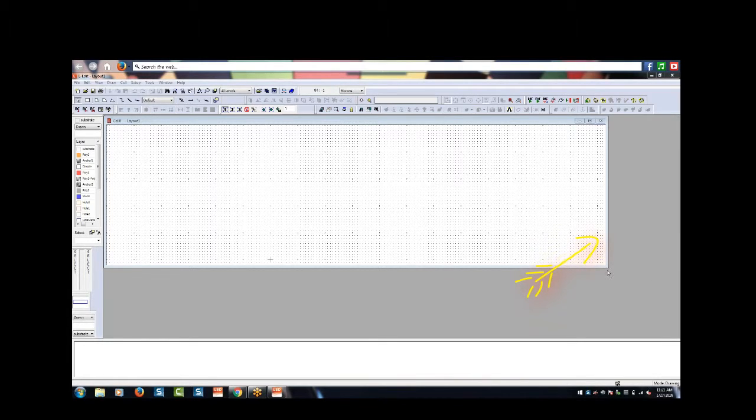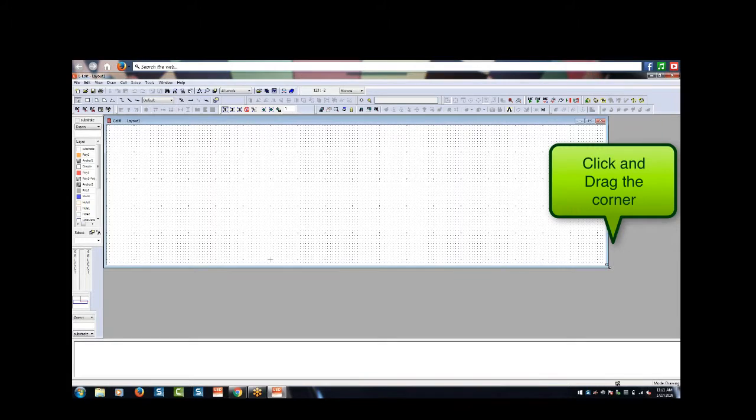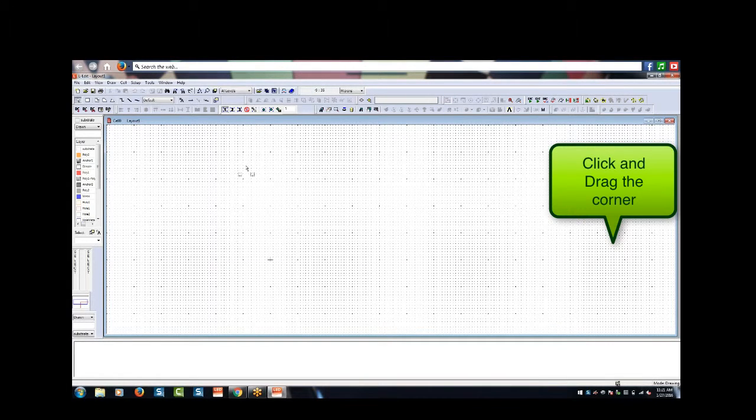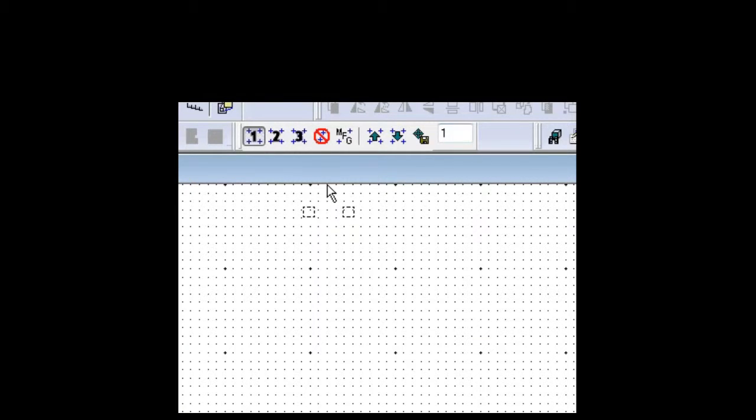Once it comes up, you can adjust this window to fit the whole screen. You can see, hopefully on your computer and on your projection screen, little dots. That's a grid. And you can play with grid sizes and customize it, and you can turn the snap on or off. So right now the grid snap is at 1 micron. You can see 1 micron here. And if you select this one, it's 3 microns. You can see it's snapping in bigger steps.